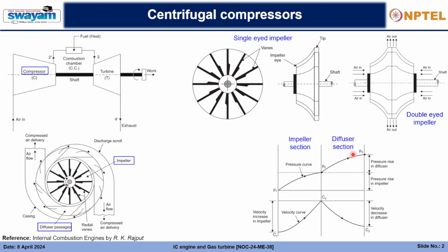If we need to build in higher capacity, we will have to do multi-staging, and that way we can use more than one compressor unit in order to increase the pressure. So it will have one more impeller and again one more diffuser. Like that, we can increase the staging units and accordingly the pressure. So that's about the compressor arrangements.